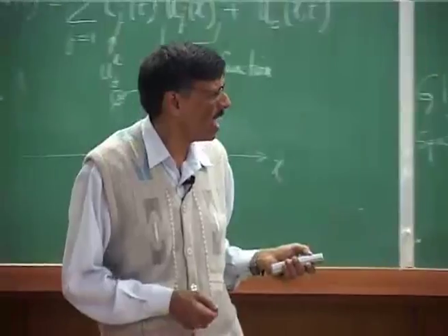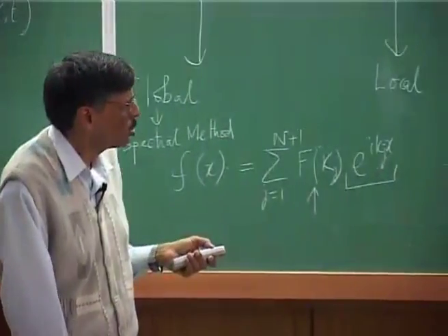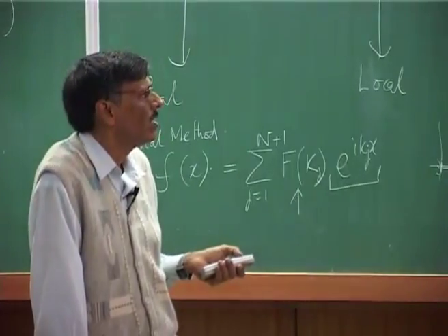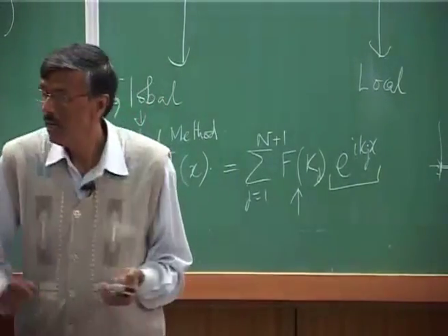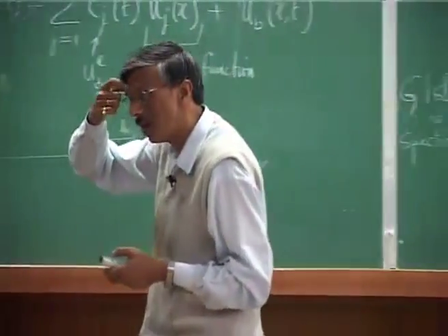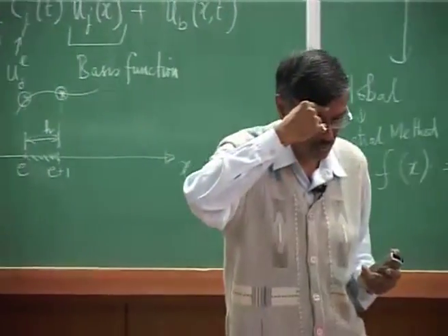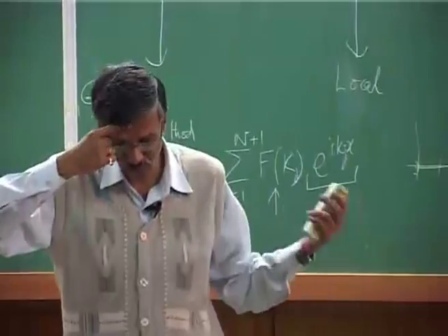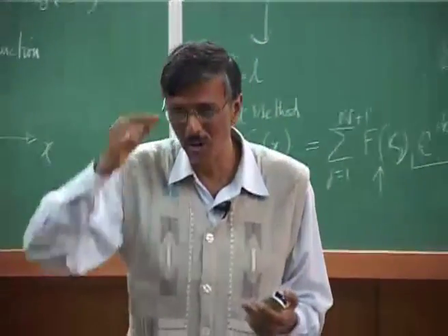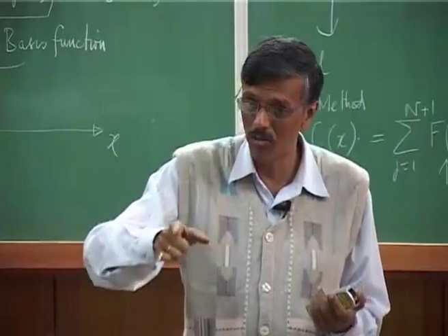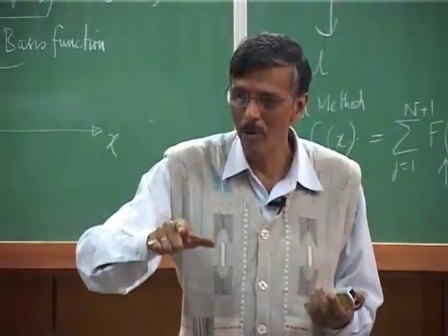So, one of the things is to show the convergence of the solution; this approximate solution must be continuous and differentiable in the weak form also. You understand that the essential difference between strong form and weak form is this: in the strong form, whatever may be the order of derivative in the differential equation, you expect that out of your approximate solution.